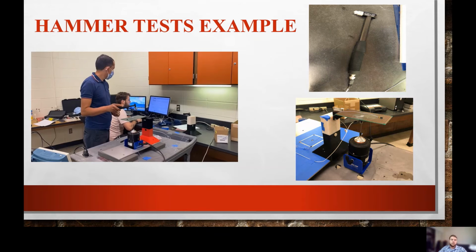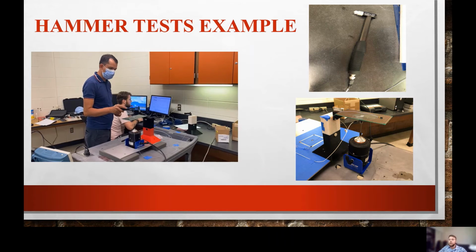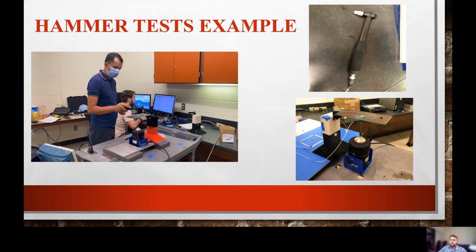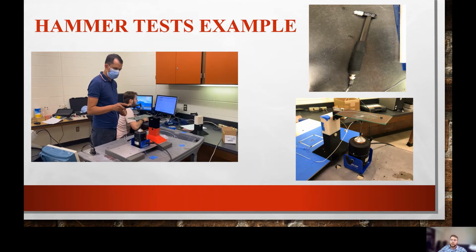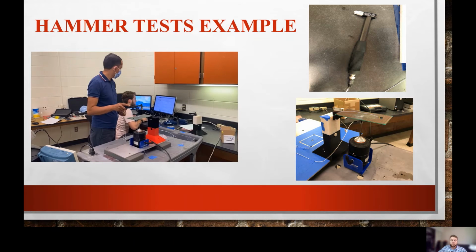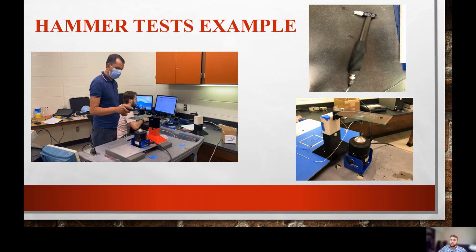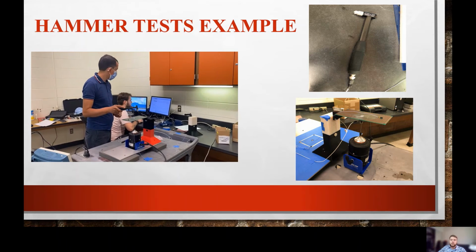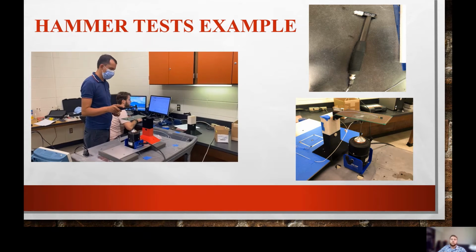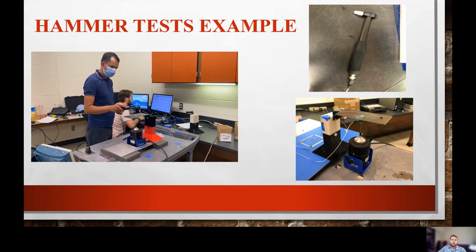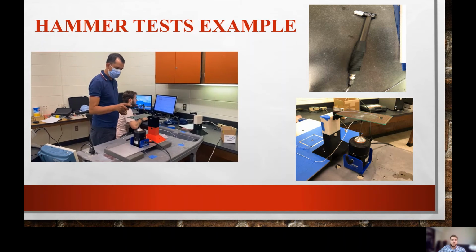Now, here's a quick example of our first test, which was our hammer test. The video on the left you can see is Dr. Doranga and myself doing the testing for the hammer test. He is applying the forces and actually creating the raw data, and then I am looking at the computer and registering the data to see if there's any values that didn't work right, or Dr. Doranga double hit the PCB so that would create nonlinear responses and make them non-valid.